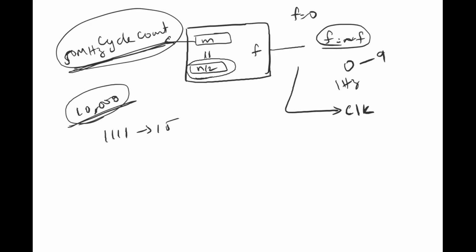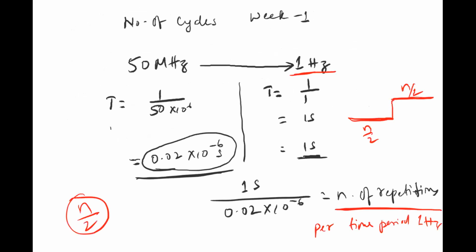But when you're using a test bench, like a Verilog test bench, what you'll basically be doing is artificially generating a 50 megahertz clock. So for that, you need to go back to this particular place where you say you're waiting for half of this time unit, and you say always #half of this time, clock is equal to inverse clock. So something like that. Does that make sense? Yeah, that makes more sense. Thank you. All right.